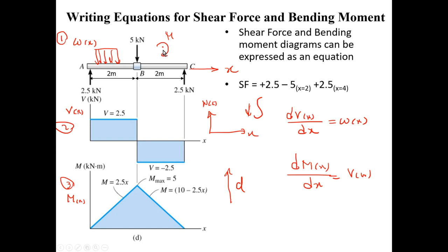If I did have a point bending moment, the discontinuity would have been visible on the third diagram, not in the second diagram. So this is not the case here. In this case, we have the bending moment continuous, but if we had a point bending rotation somewhere along the beam, the result would have been visible on the third diagram.